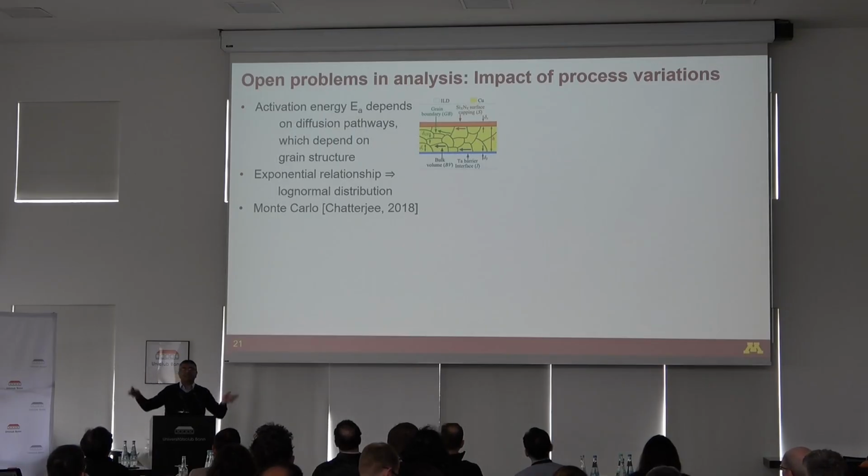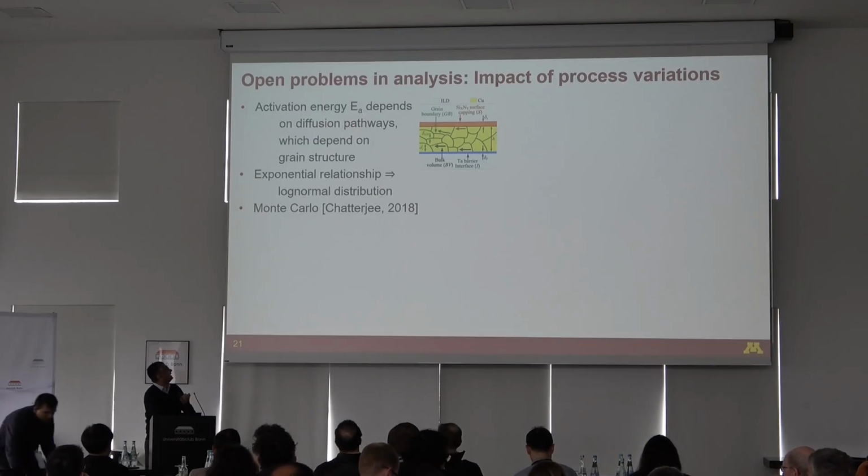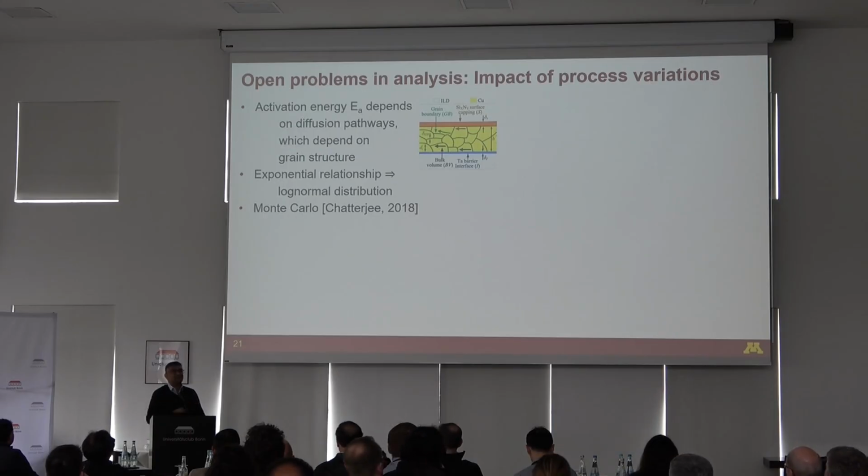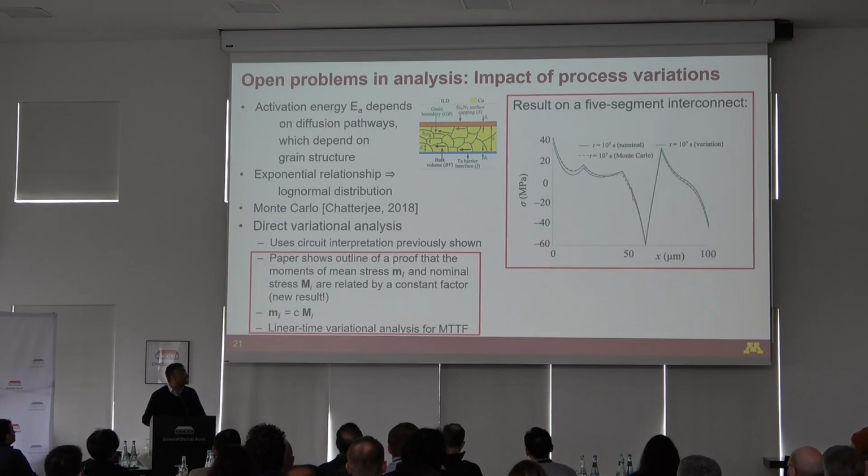So this means that you can never completely determine this, and there is this activation energy parameter, which is seen to be a Gaussian distributed parameter. There's some nice work by Farid Najm's group where they built an EM analyzer and put Monte Carlo around it, which is fine, because if your analyzer is fast, you can do Monte Carlo, but you've got to be able to do better.